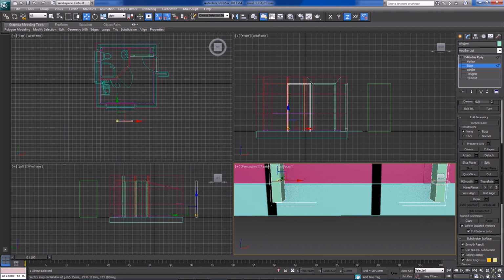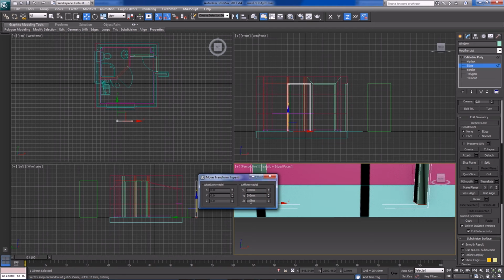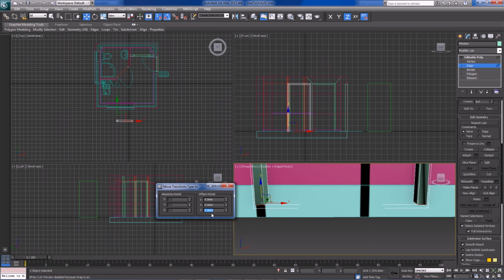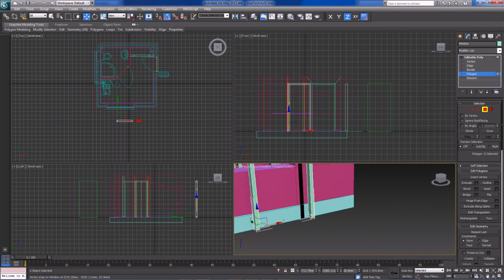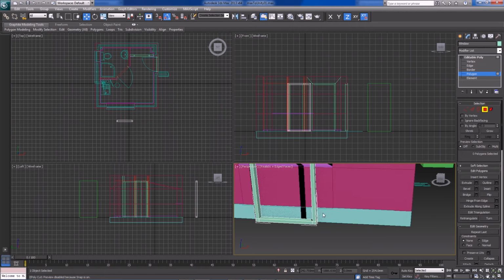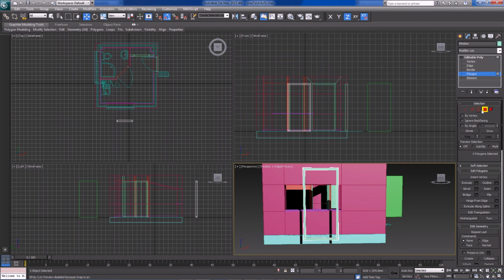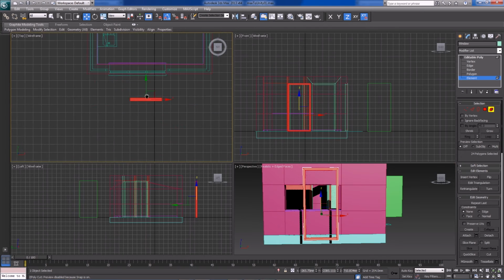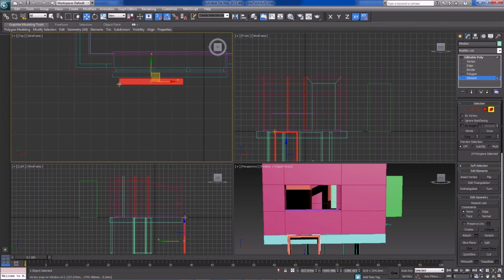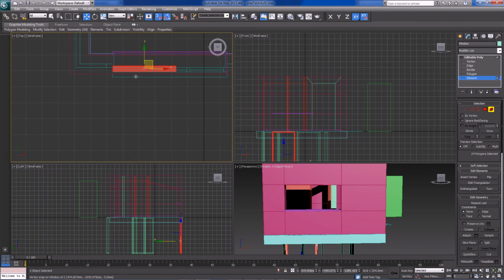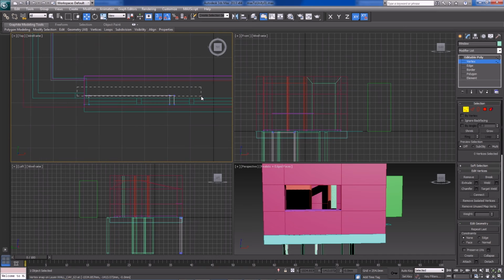And to make sure they are precise, which is 52 actually millimeters from the bottom, just move them to the bottom, then hit F12, then move them 52 millimeters up on the z-axis. And that looks about right. Click here, select these two faces and bridge them. Here we go. So let's move that in place on these two axes. Go into Vertex Mode.